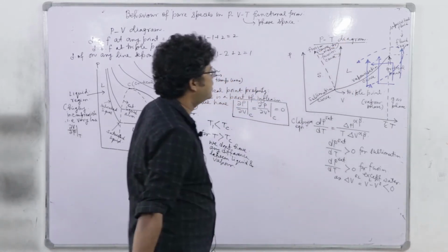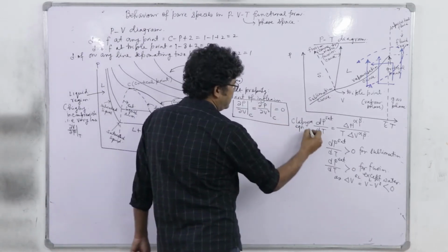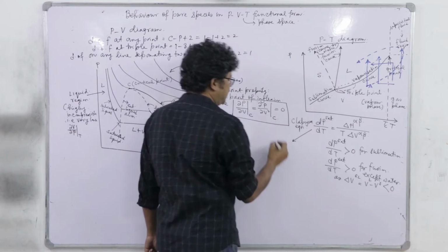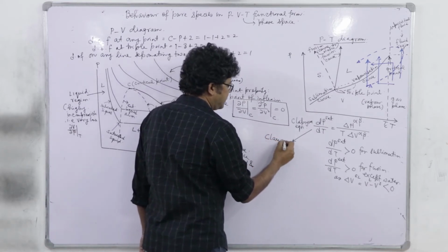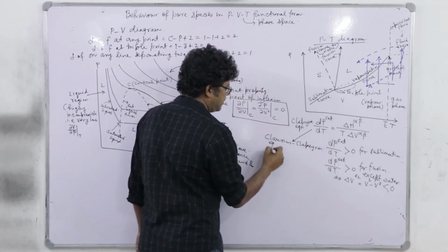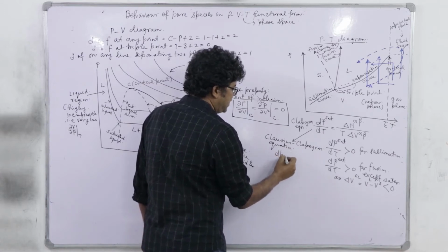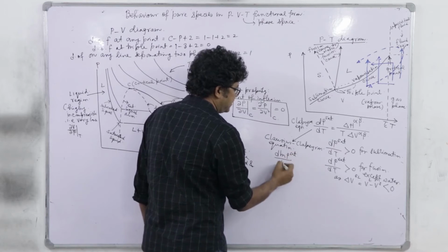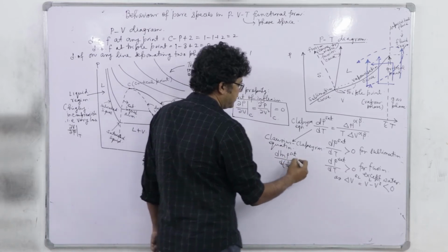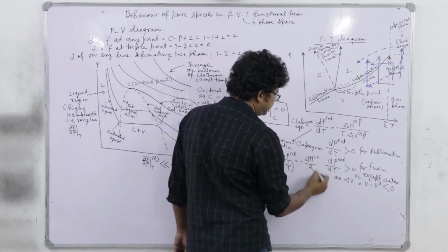Right? Now, regarding vaporization, we have this Clapeyron equation, and also over this narrow region, maybe over here, we can use this Clausius-Clapeyron equation, which states that d ln Psat by d of 1/T equals minus ΔH LV by R, right.